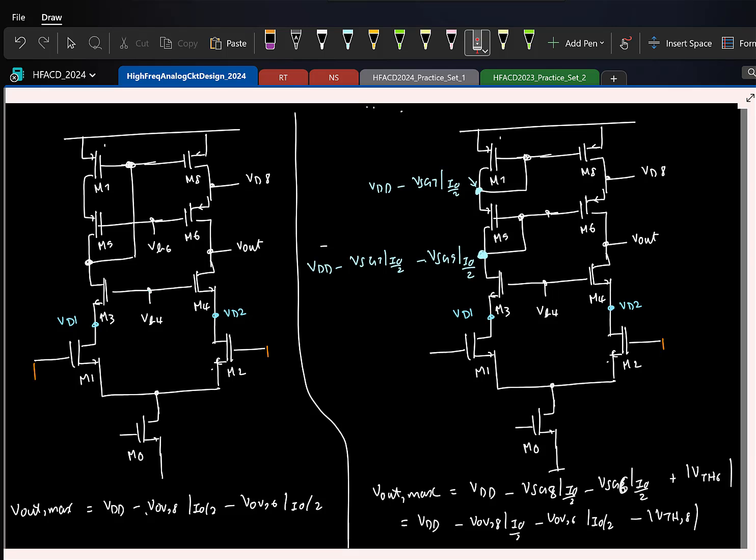Also, when designing transistor going out of saturation, what do you think? No, you should make sure it doesn't go out of saturation. So I didn't understand the range question. Which range? This range. No, this is actually not so small. I mean, overdrive can be as small as, let's say, 50 millivolts. Let's say threshold is 400 millivolts. If you have a supply of 1.8 volt, it's reasonable. Sometimes VGS minus VTH comes very small in simulation. No, VGS minus VTH, it doesn't just come. You set it for something, right? If you have not designed for an appropriate VGS minus VTH, you will not get it. Gate to source voltage is set by the current and the sizes, right? You have to design it accordingly.